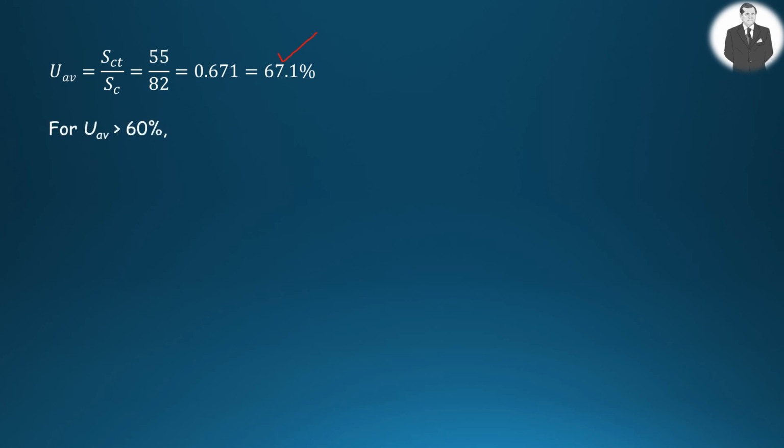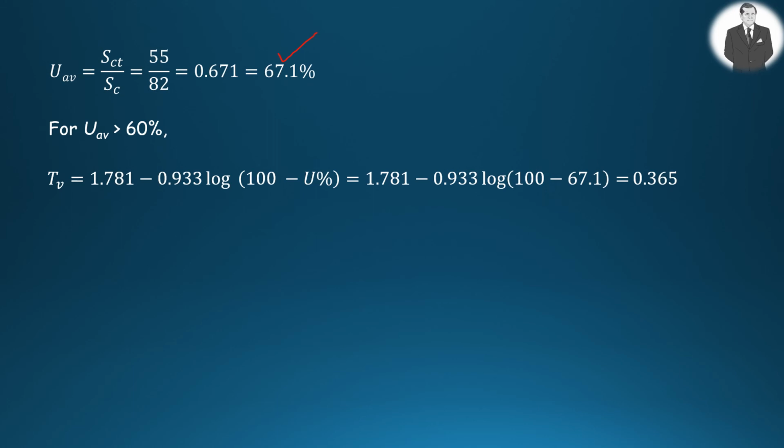Since it is greater than 60%, the equation to calculate the time factor given here should be used. And the time factor can be obtained as 0.365 accordingly.